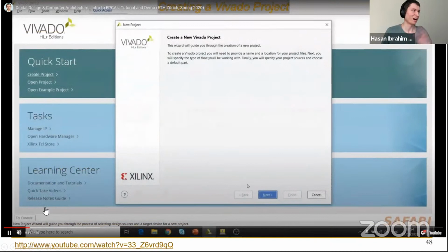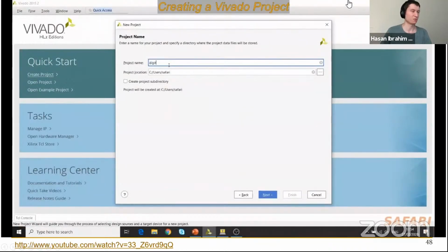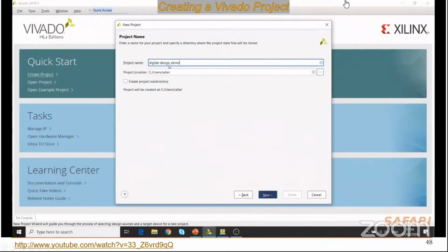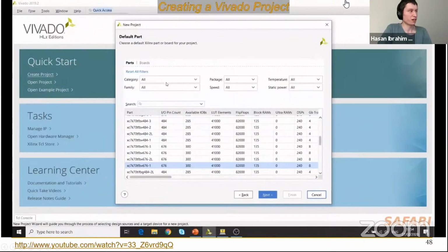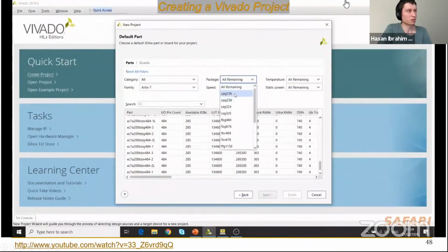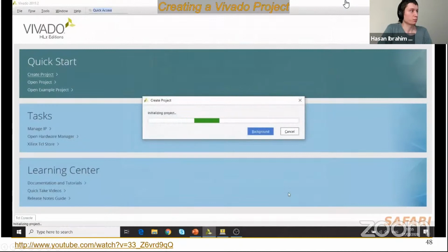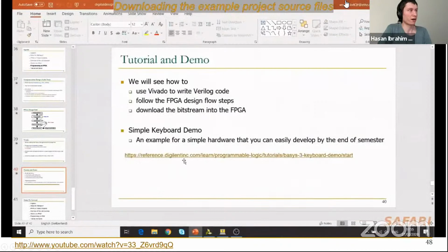My bad. Okay, I will explain things as the video goes. First we start with creating the Vivado project. As we do in other IDEs, we name our project. Here we select an RTL project, and in this step we will select the FPGA that we will be working with. We will also have a link to the video on the website, so you don't need to memorize any of this, obviously. And after creating the project, we will start with adding the files.